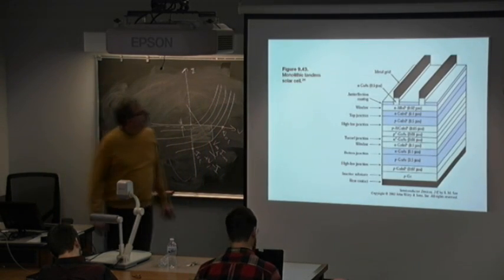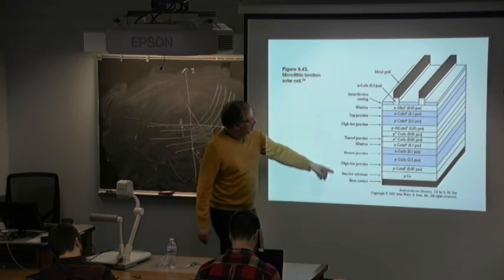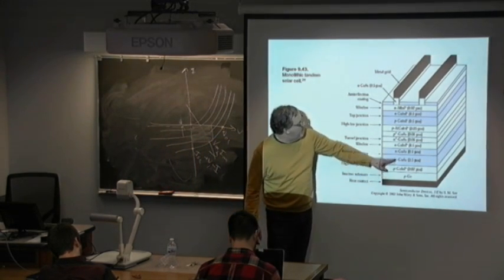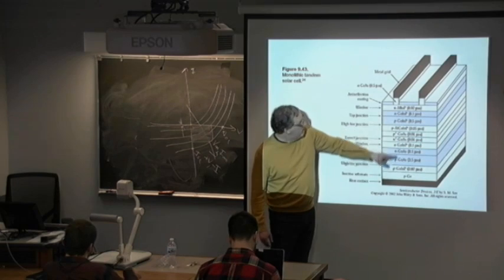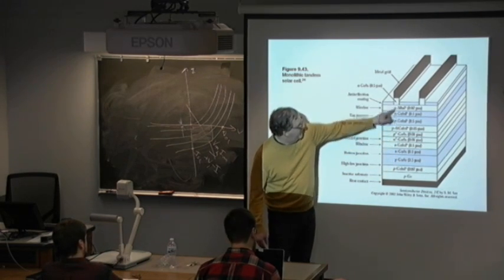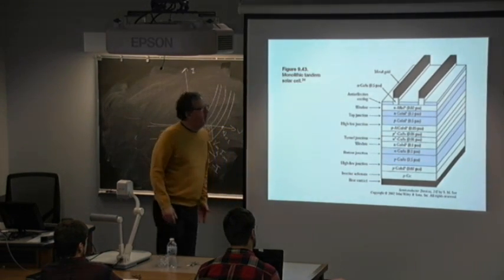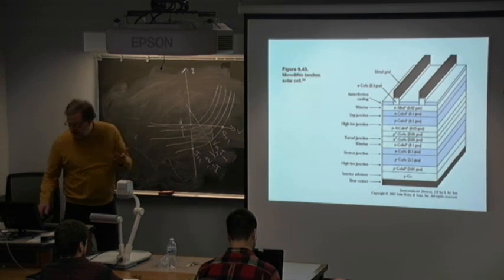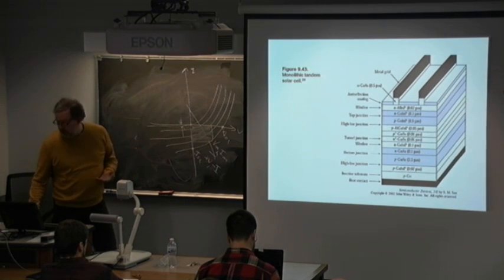Here's the triple junction monolithic tandem solar cell. Of course, we have to belabor all the lattice matching as we go across these different material systems. So I have to worry about exceeding the critical thickness and creating misfit dislocations.